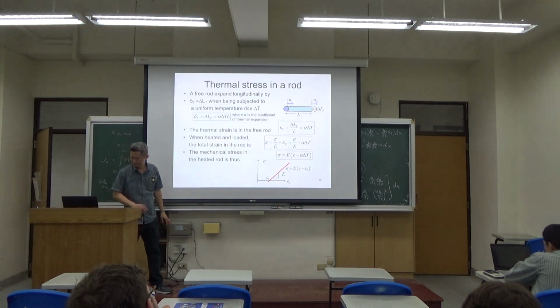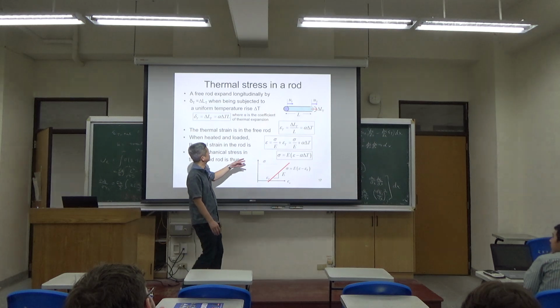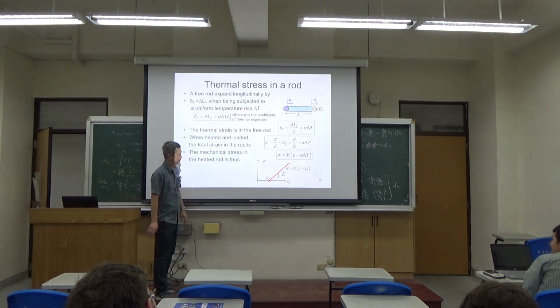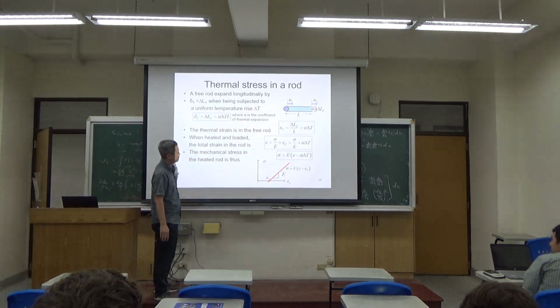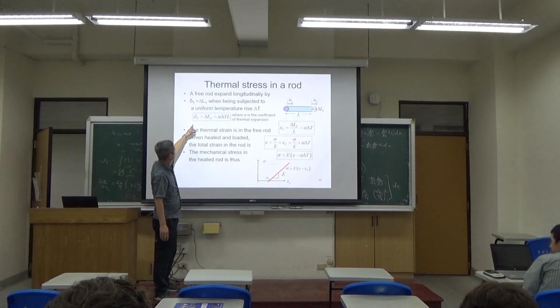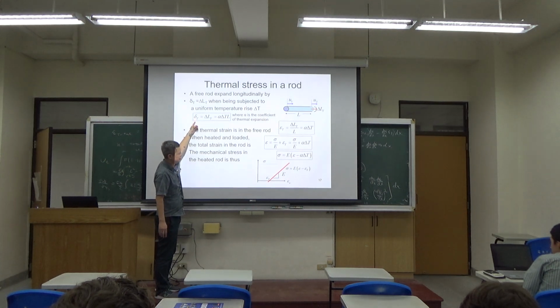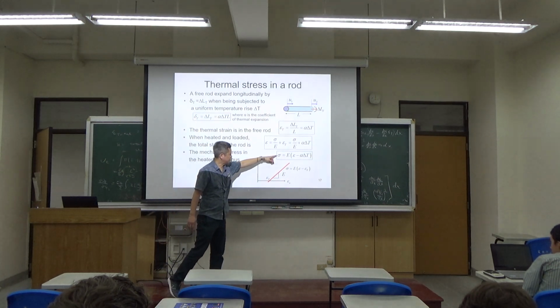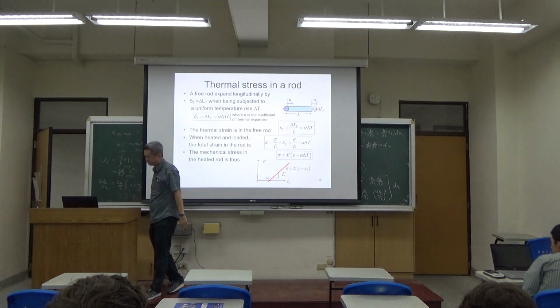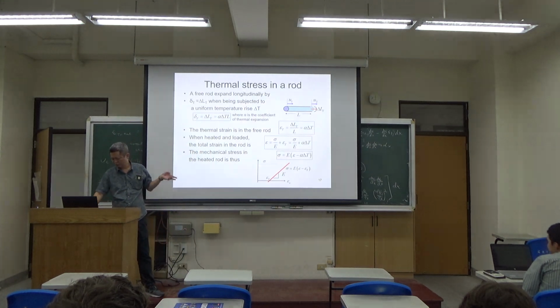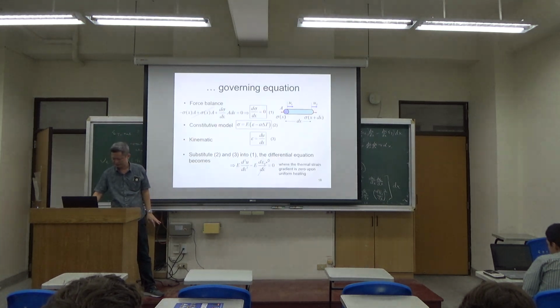So next, we also try to tell you about thermal stress. Thermal stress: you know about thermal expansion. The actual mechanical stress is the modulus times the net mechanical strain, that is, the total strain minus the thermal strain.